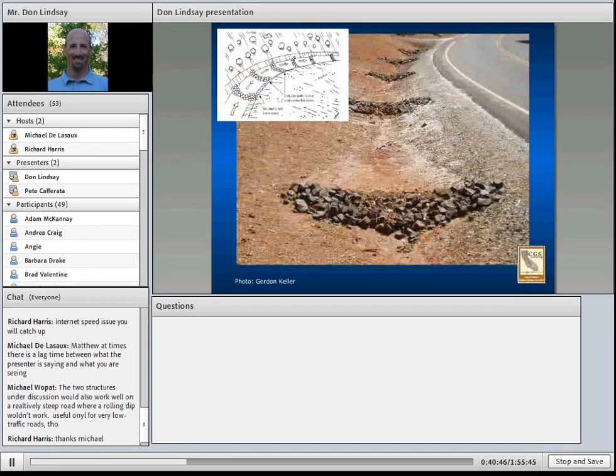Ditch dikes or check dams are another form of erosion control for ditches. Check dams reduce scour and channel erosion by reducing flow velocity and encourage settlement of sediment. A check dam is a small device constructed of rock, gravel-filled bags, logs, fiber rolls, pretty much anything, that is placed across the ditch. Typically, the center of the dam is the low spot, allowing water to be concentrated over the top of the dam and not allowing the water to flow around the edge of the dam.